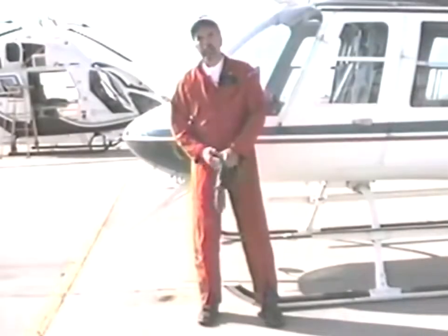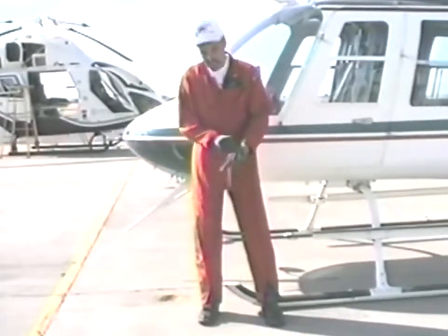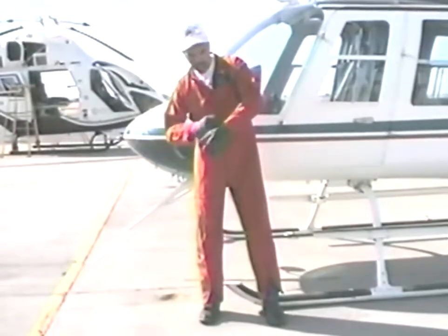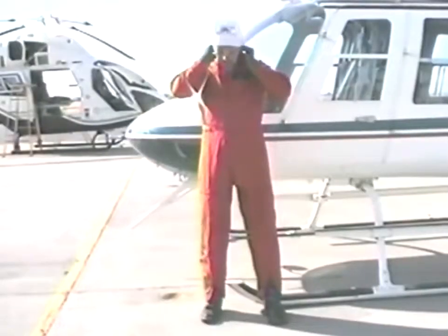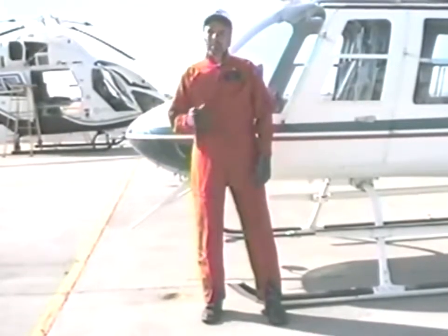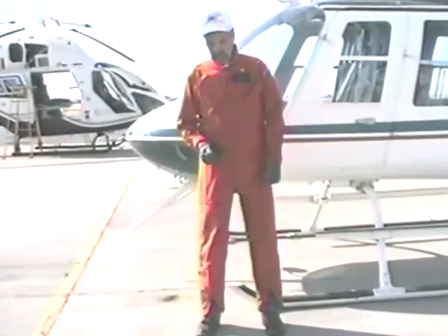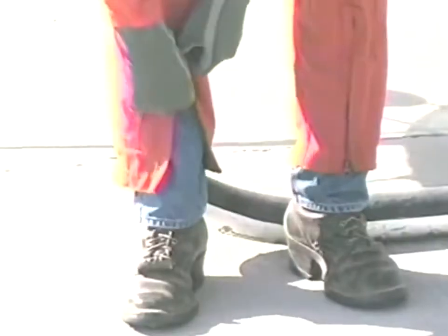If you're going to wear the protective clothing, you need to know how to wear it right. What's right? Well, let's start with the sleeves. Sleeves should be down over your flight gloves and securely fastened. Next thing you want to make sure is that your flight suit or your fire shirt is zipped or buttoned clear to the top, and that your collar's turned up. The name of the game here is protection. You're trying to protect yourself against the possibility of a post-crash flash fire. So you protect yourself as much as you can. Also, if you've got zippers in your pants legs, zip them down to where they're snug at the bottom.